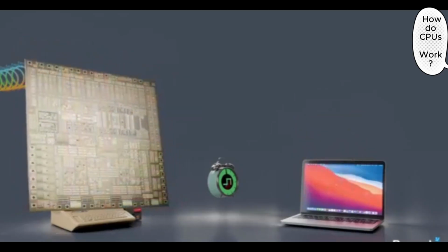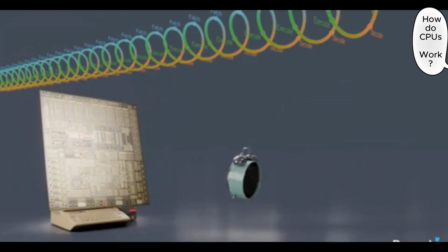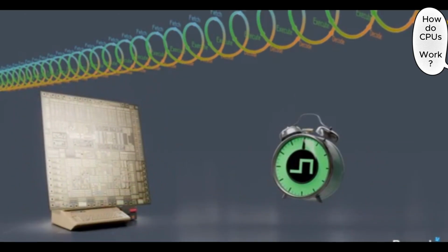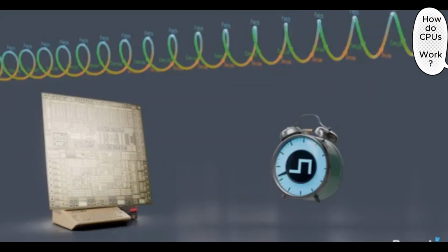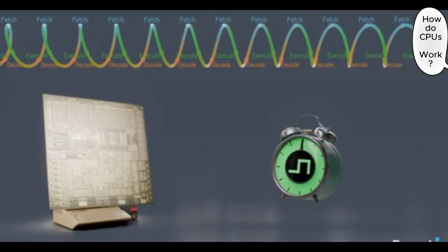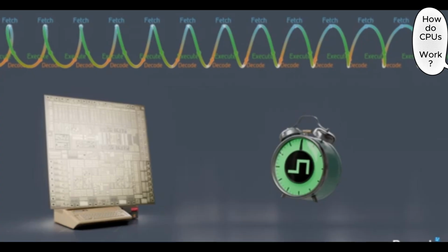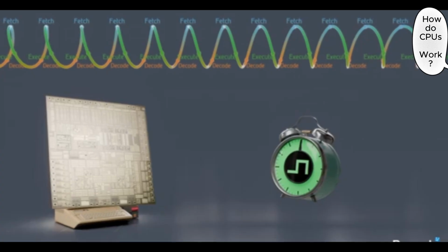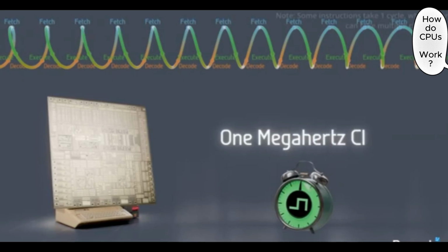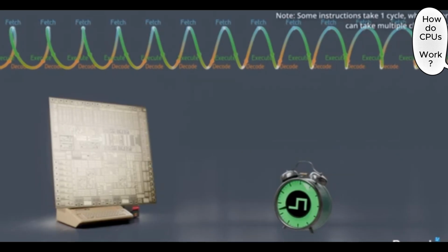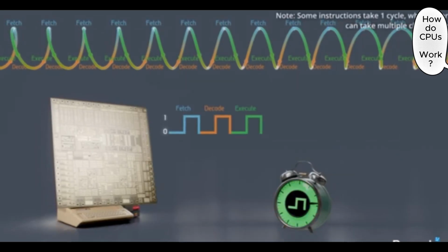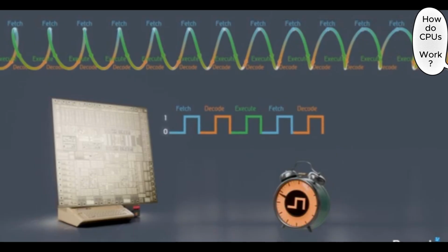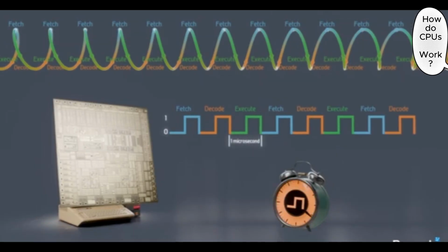We'll explore the exact differences in a few minutes, but for now, one important detail is that the fetch, decode, execute cycle uses your computer's clock to regulate its pace. The 6502 chip had a 1 MHz clock, which ticked away at 1,000,000 times a second, and thus each step in the fetch, decode, execute cycle took a microsecond.